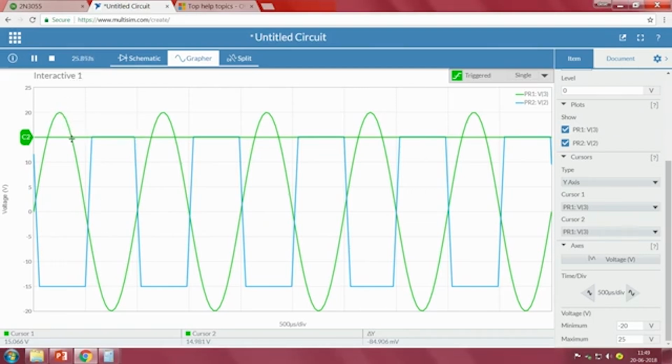When it is lower than the lower threshold value, it starts pumping current. As a result, it starts heating. So, the duty cycle, or the frequency at which it switches on or off, entirely depends upon the rate at which your input is heating your plant. So, this way we can understand how exactly the Schmitt trigger can be designed based upon the requirement.